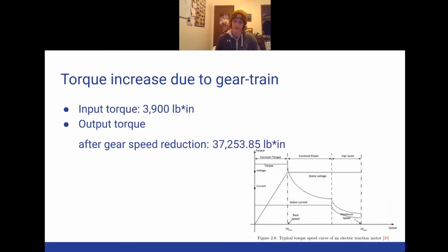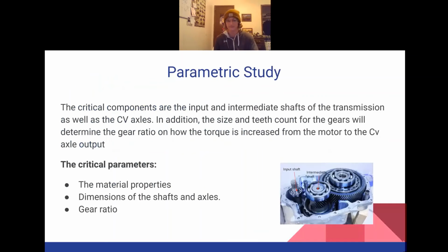This increase in torque via a single gear is an advantage of electric vehicles over internal combustion vehicles, as the maximum torque of the engine is provided at low RPM, practically from a standstill, meaning multiple gear ratios to achieve a narrow optimal torque curve like that of internal combustion motors are not necessary, and the high angular velocity output capable from an electric motor means that no overdrive is required to maintain a higher velocity.